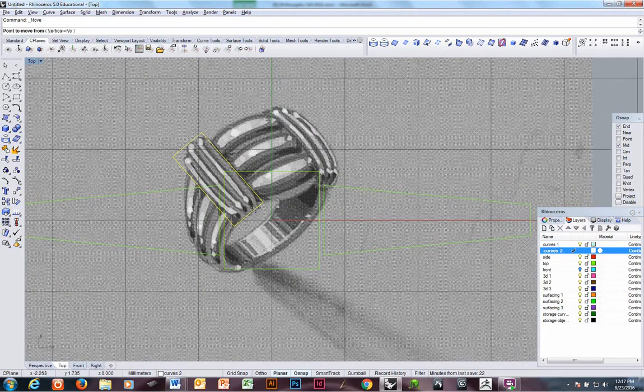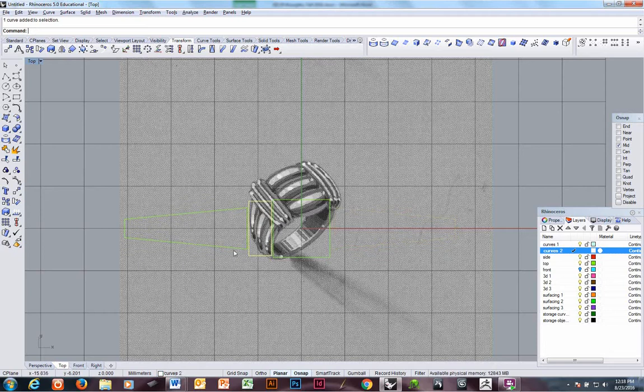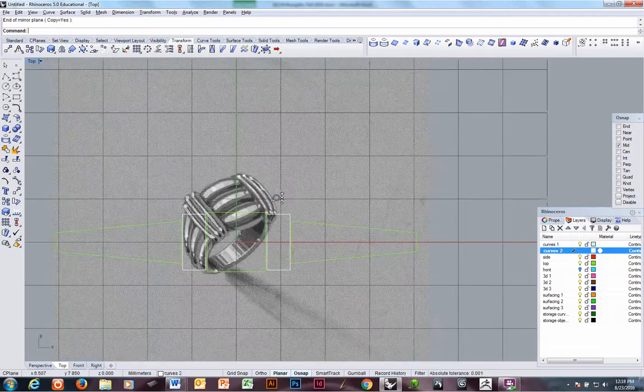All right, I'm going to move this into position. This collet or cuff, center snap, 0, and once again, rotate. Grab a mid snap and shift key. And I'm going to move this out. Now in theory, this should come right up to the edge of this. I'm going to leave a little gap. And a little gap. I should have used history when I mirrored. That would have moved up automatically for me. I'll do history now in case I need to make further adjustments.